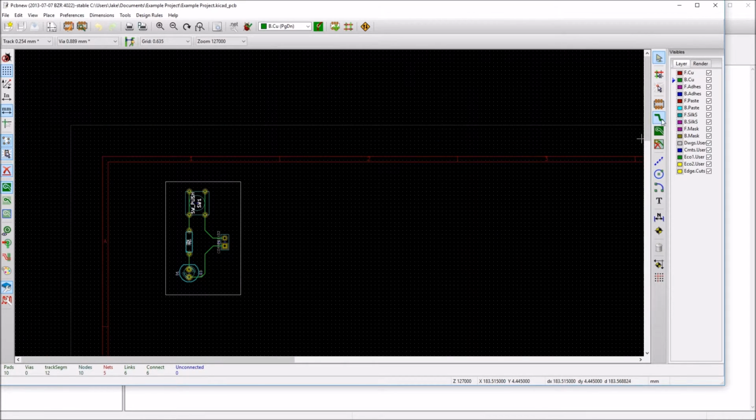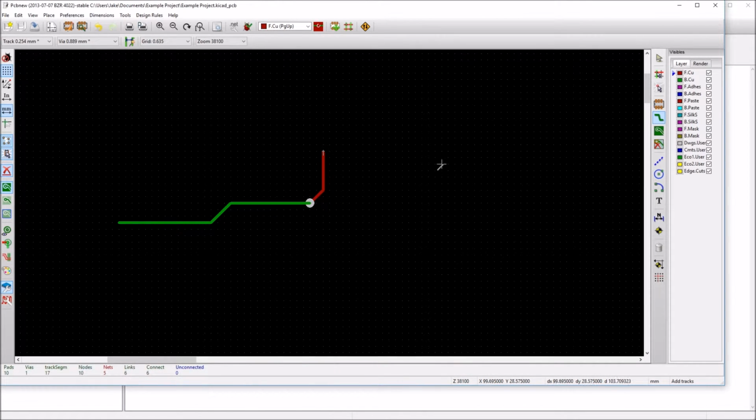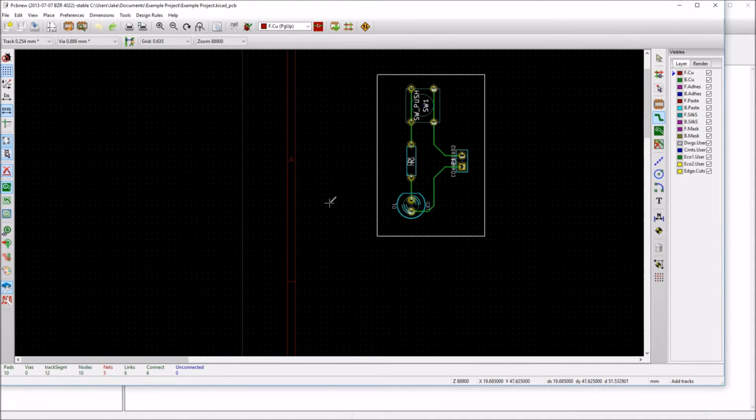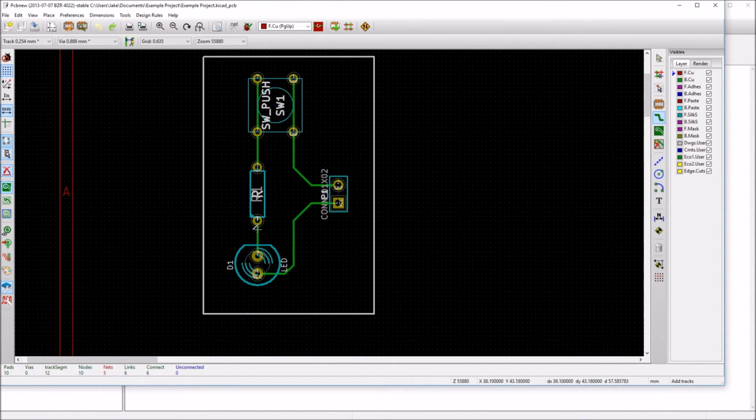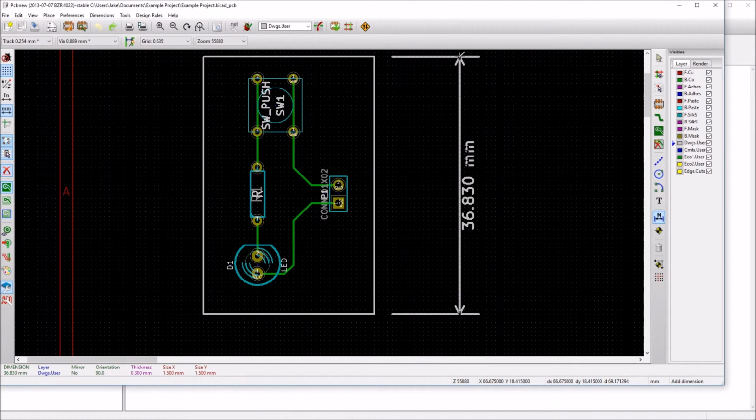You've got your wire routing, pretty standard. You can press V to place a via, which allows you to go from one side of the board to the other in a track, which is very good. All your basic layout stuff. A really nice feature about KiCad is they actually have a ruler, where you can measure out how big your board is, and that's good for telling the manufacturer how big you need to make your board. You can do rat's nests. There's pretty much anything you want you can do.